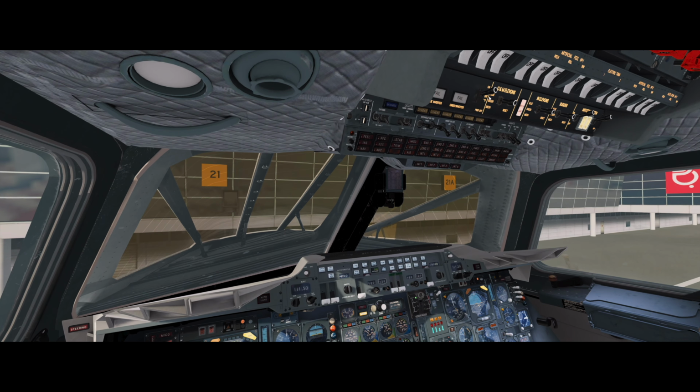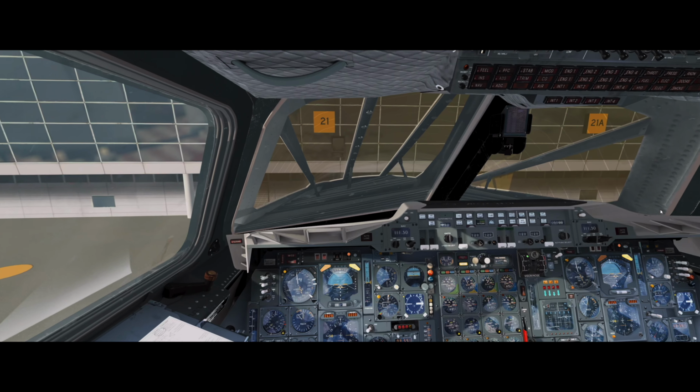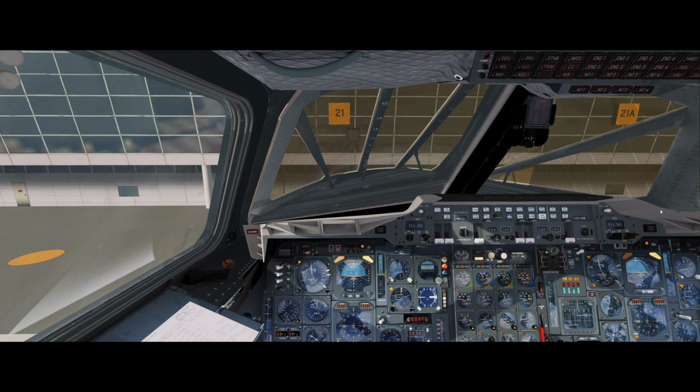Once we get the hydraulics running, we can click these ground hydraulic switches to the blue system. You can take the reset ground electrics away. Make sure to hit the mechanical jam button, or else your autopilot might not function when you are flying. Make sure to click every single one of these switches for the fuel, electric trim, artificial feel, or else your systems may not function as intended.